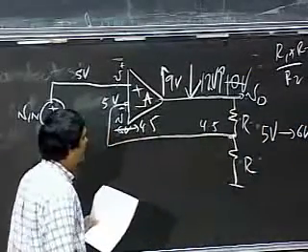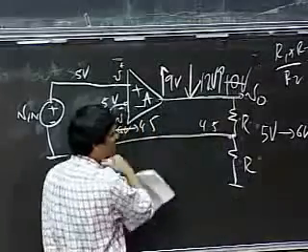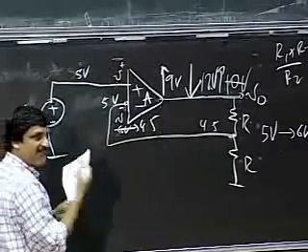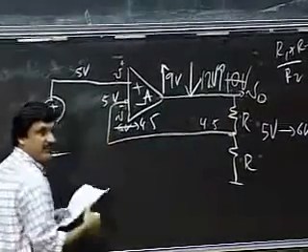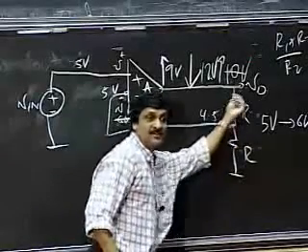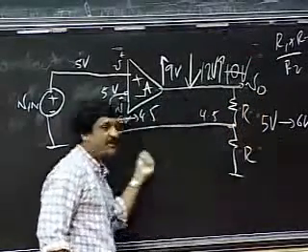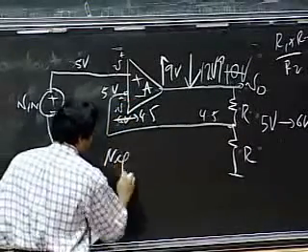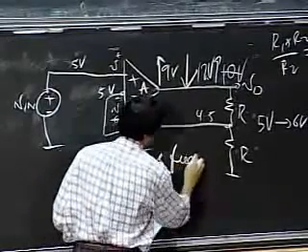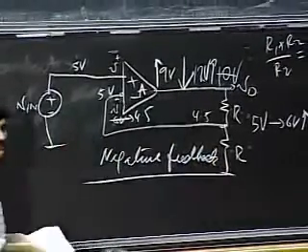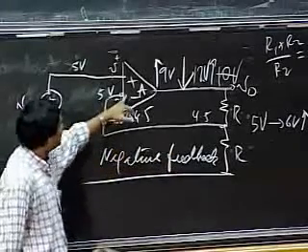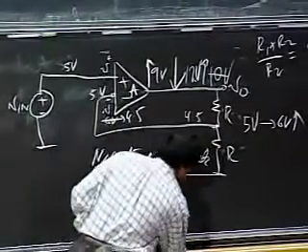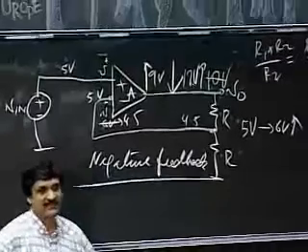And what's happening is that in this arrangement, I've fed back a portion of the output to the negative input. By providing this feedback of a portion of the output to the negative input, I've arranged it in a way that I have something called negative feedback. What negative feedback does is that if this wanted to go wild and crazy, the circuit provides it with some negative feedback, like you just saw. Feedback, a big word.